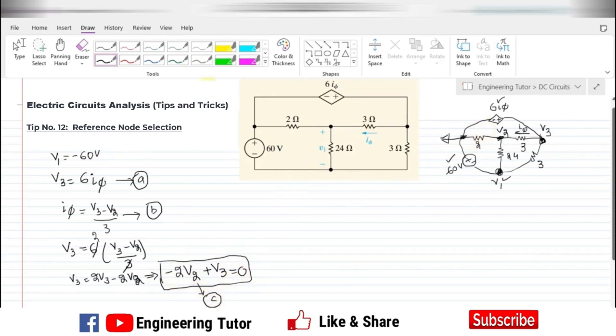Now move towards node V2. Here we have some currents. First current is here, second one is here, and third one is here. Let me call them I1, I2, and I3. At node 2, applying KCL, I get I1 plus I2 plus I3 equal to 0.